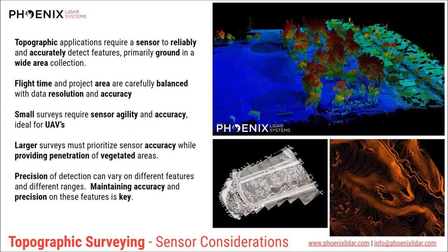And one other essential thing to think about is, while we are speaking solely about LiDAR here, are you going to be co-acquiring with imagery of any sort? And if you are, there's a very good chance that the camera footprint is much smaller than your LiDAR, thus reducing the effective acreage able to be covered by the LiDAR.